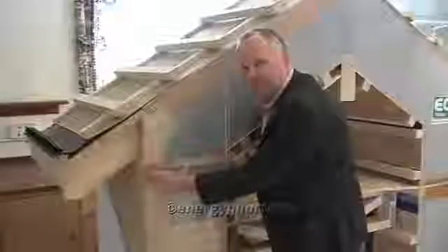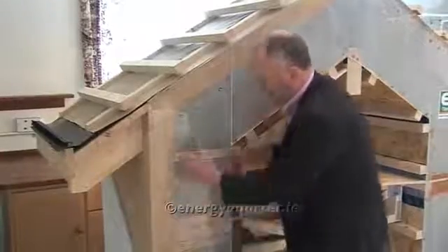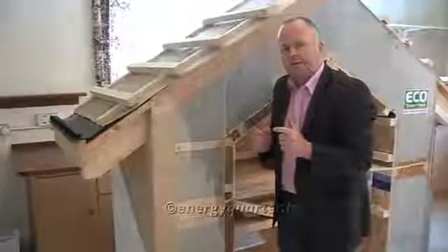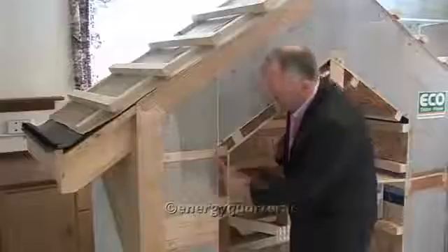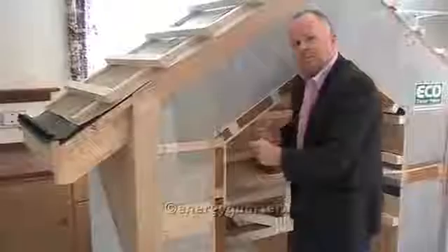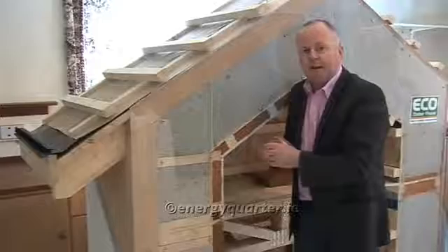On the outside of this then we have about 100 millimeters of fibre-based insulation, and you can see that running down along the entire structure, and you just can get the impression that this insulation here is preventing any cold bridging through this timber stud-work. And the last and third layer of insulation, which is very important, is on the inside of the house, and this is what we call a service cavity, and this allows us to create an airtight layer here, and this is our service cavity where we can pull pipes, wires, any sort of conduits without compromising the airtightness.